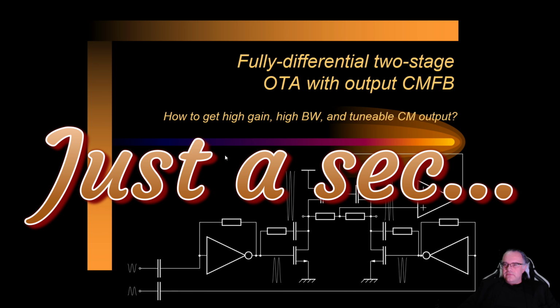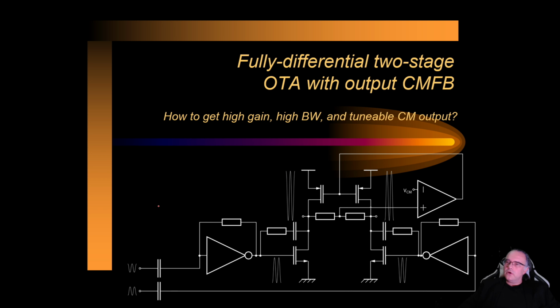This architecture is defined for operation with differential signals. However, real voltage signals always have differential components and a single-ended component, or the common mode component. Here, the differential components are demonstrated. We get two signals which are 180 degrees phase rotated. So if one is increasing, then the other will be decreasing. Only the difference between these two is defined as our signal.